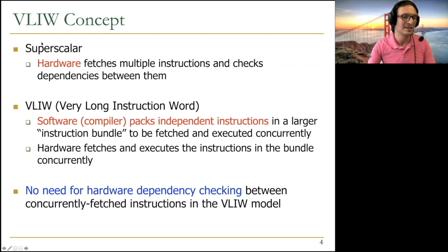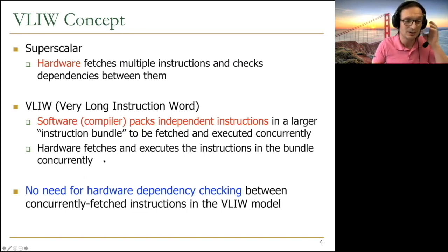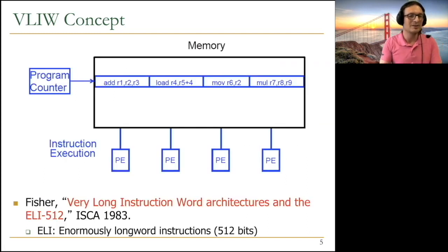And after learning superscalar, VLIW is not a huge step in a conceptual manner, of course, but the thinking is very different. And because the principle is that software needs to do all the dependence checking and ensuring that the instructions can be concurrently executed, now the software needs to be very intelligent. Okay, so this is a pictorial view of the VLIW concept.